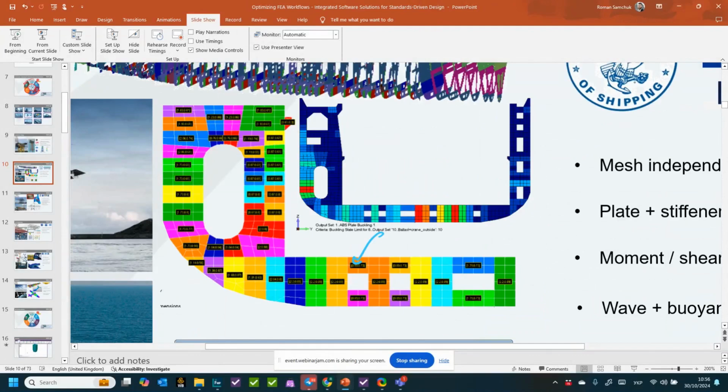Of course, there is an option. For example, if you don't like a certain plate thickness in your plate field or this local plate, you can change it without changing your FEA model. So change it for the check, yeah, with a certain thickness factor, let's say. So you say, okay, this plate is corroded and I want to reduce this plate thickness. This can be done as well. But the basic dimensional characteristics are accounted for automatically by the software, whether it's a beam where you have to define the beam buckling length in different directions, joint, weld, and so on.